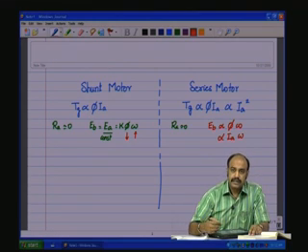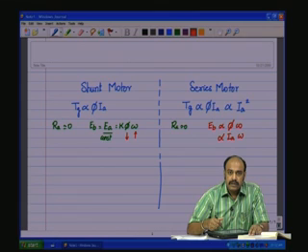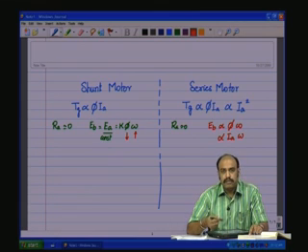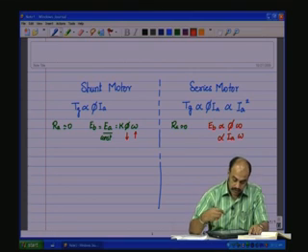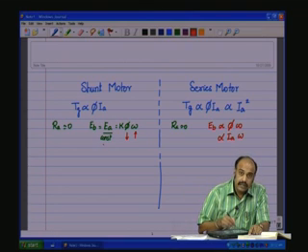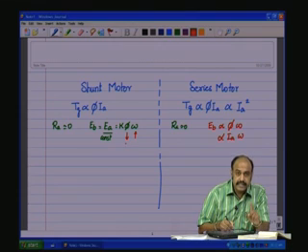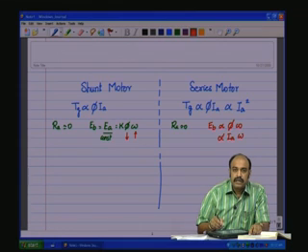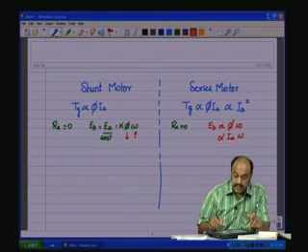But under loaded conditions, the torque will develop and then settle down at the operating point depending upon the load torque requirement. So, the runaway situation can occur in both the cases. In the shunt motor, the runaway is the case when the field winding gets cut, under no load, when you switch on the armature voltage EA.